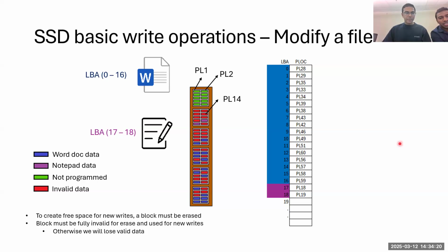An interesting point I want to add here. Do you remember we used to right-click and safely remove the pen drive? When we do that, it sends a signal to the flash drive that whatever volatile memory you have in the DRAM, just push it to the NAND. So NAND will have some system blocks as well, not just the host data, so that next time we power on or connect the flash, we recreate this table from the NAND.